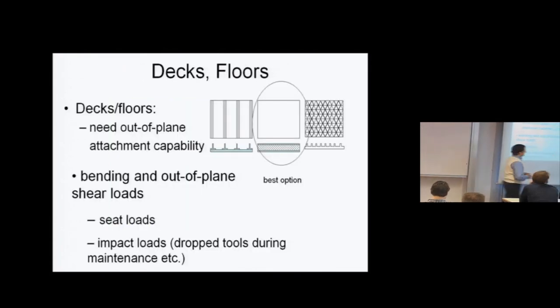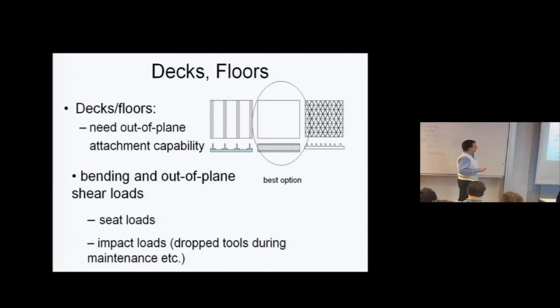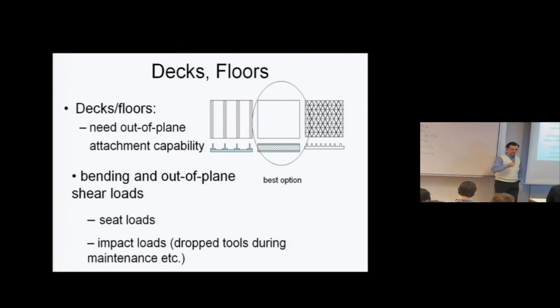Decks and floors are just glorified skins which can have different designs. Remember the stiffened design, the sandwich design, the grid stiffened design. And you can have both in-plane loads and out-of-plane loads. Walking loads being one of the significant ones, and seat loads being another one in the floor. And of course, impact loads, drop tools during maintenance, and so on. We'll cover impact in the second part of the course in much detail.